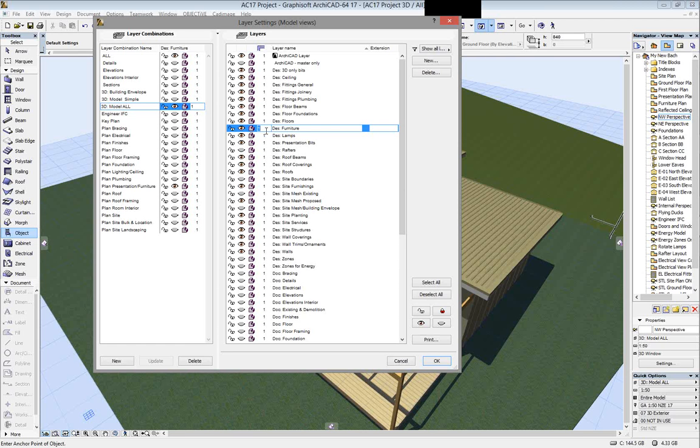A classic case, historically before the renovation tool came out, would be to get your demo walls not intersecting with your new or existing. So create a new layer called walls demo, set the intersection layer to 2, then they never clean up. There can still be ways of using those currently in ArchiCAD, so that is still your main connection priority.